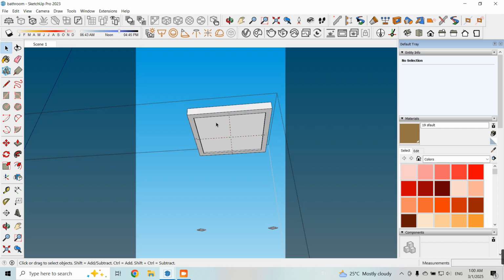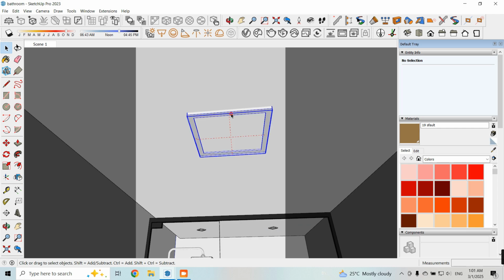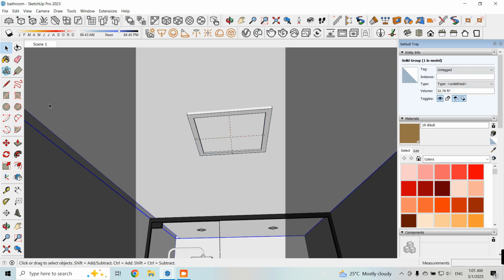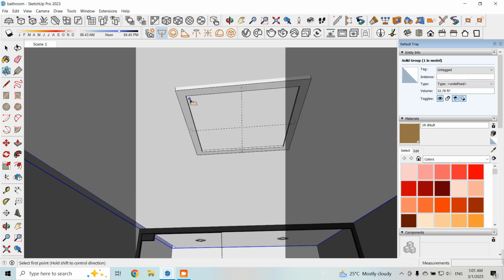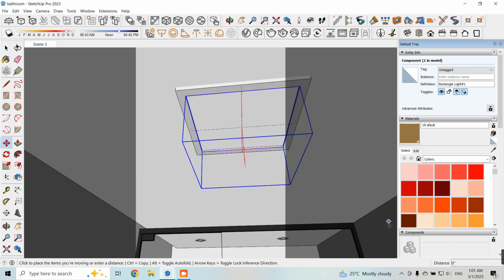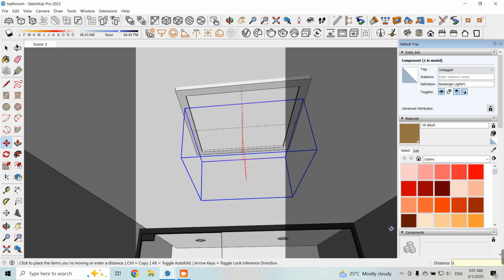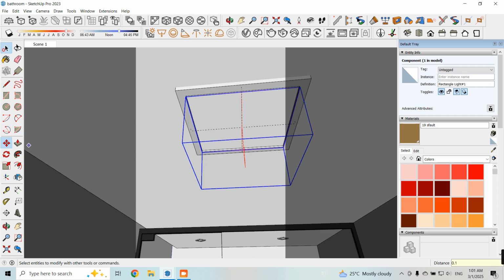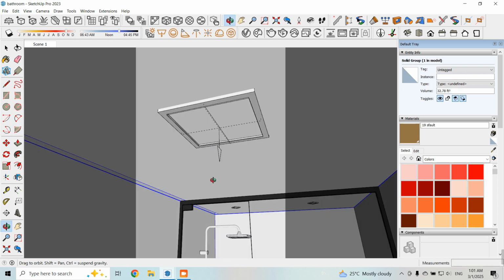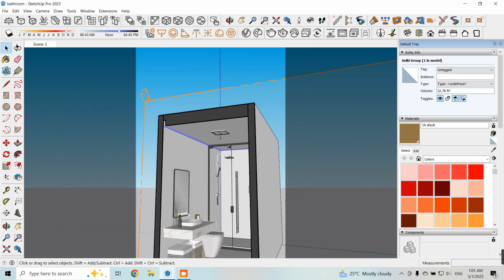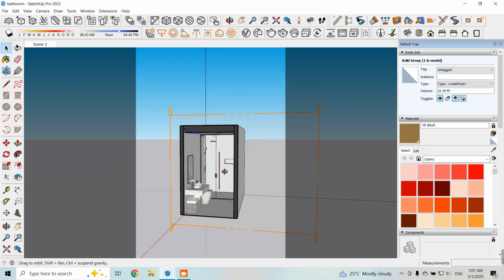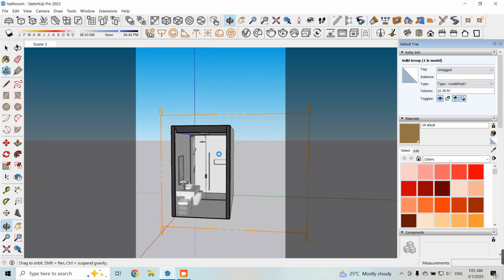Okay, and then I want to add a rectangle light to this surface. So call rectangle light and then move the rectangle light a little bit downward from the keyboard, 0.1 or 0.2 is good here, because the rectangle light is the main light that gives light distribution to this room.